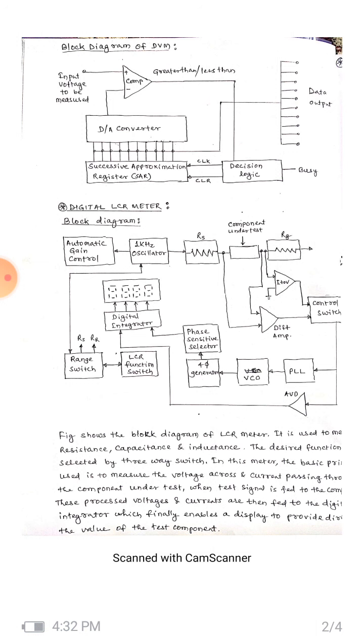So if the comparator output is low, then the decision logic clocks the next state, and the SAR output is the next guess. Depending on the output of the comparator, either low or high, the decision logic is going to display the two clocks here. If the comparator output is high, then the decision logic will clear the last state, and the SAR output is the next guess.